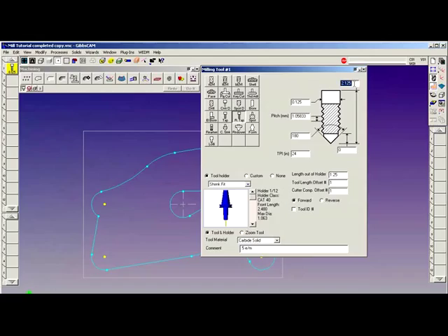Now, tap definition, pretty much the same: overall length, diameter, the pitch, or the threads per inch. When you type in your threads per inch, the pitch in millimeters updates. This is a handy addition to the V9 software that allows you to define a metric tap readily when machining metric holes. A lot of times you get a blueprint that has all inch values for the part, but they have callouts for metric holes. We've simplified it a bit by giving you the ability to type in the pitch and directly describe a metric tap.